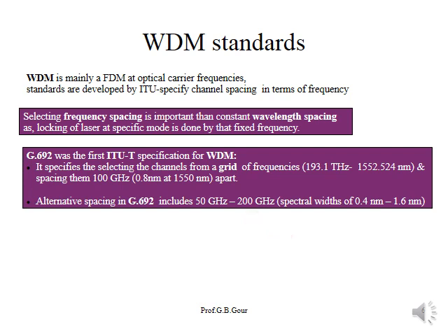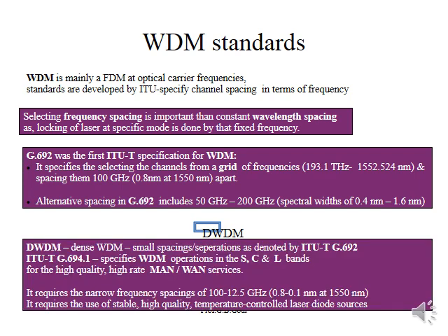Then we can continue this discussion with the two versions in WDM. One is dense wavelength division multiplexing. Its main features: compared to the previous G.692 standard, it is going to follow the G.694.1 standard, applicable to S and L bands, and its applications encompass MAN and WAN services.